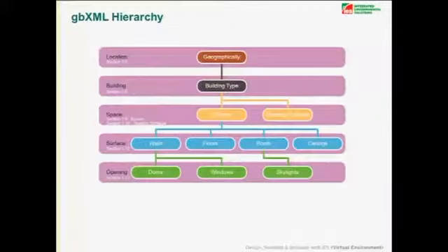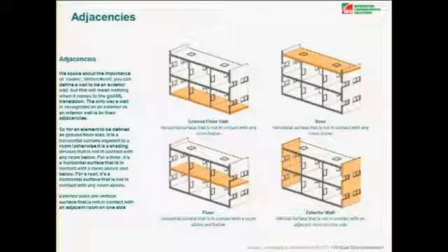And then we have surfaces, which are walls, floors, roofs and ceilings, which bound the rooms, and then we have openings finally as well. So GBXML describes elements using a common language, shall I say that? Michelle will probably correct me on that. But that's the purpose of it. The Green Buildings XML schema was developed to enable this exchange of data from architectural or 3D modelling packages into analysis packages. It's fairly simple in its approach. It's not perfect by any means, but it's what we have. It's a kind of lowest common denominator for us to work to currently. So it's kind of phase one, I guess, for us in this respect.